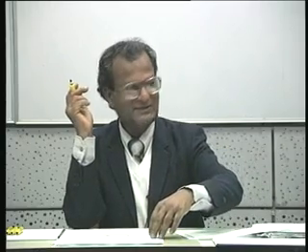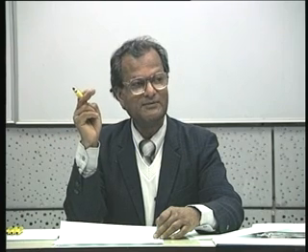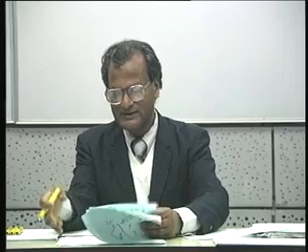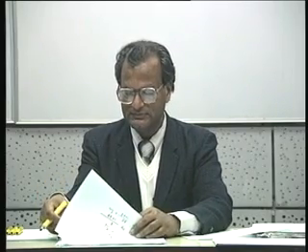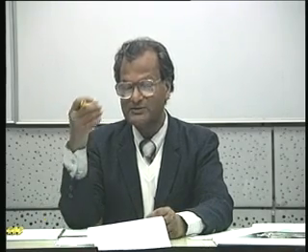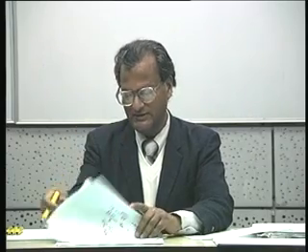Look, this is why I asked the question, we already had an example in which the parameters may not have existed. You see, look at this NIC example. S11 was n squared plus 1 divided by n squared minus 1. So when n is equal to 1, it doesn't exist. Similarly, S22 for that case should also not have existed. What about S12 and S21? Same. And therefore scattering parameters belong to the same category as Z or Y. They may or may not exist.